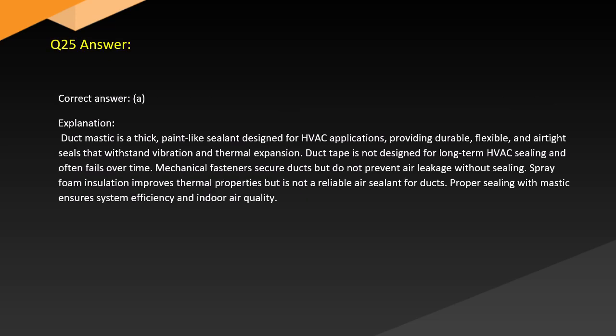Answer. Correct answer, A. Explanation. Duct mastic is a thick paint-like sealant designed for HVAC applications, providing durable, flexible, and airtight seals that withstand vibration and thermal expansion. Duct tape is not designed for long-term HVAC sealing and often fails over time.